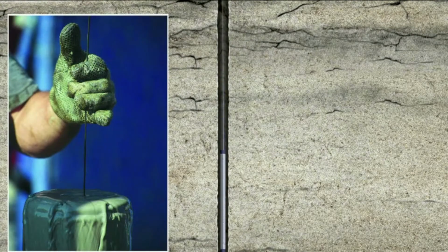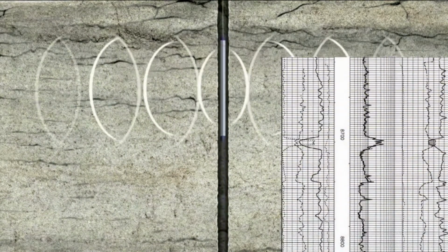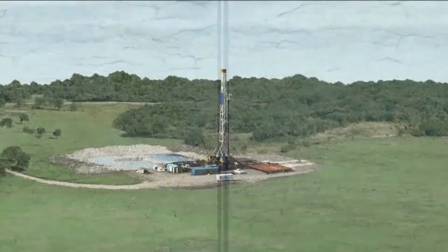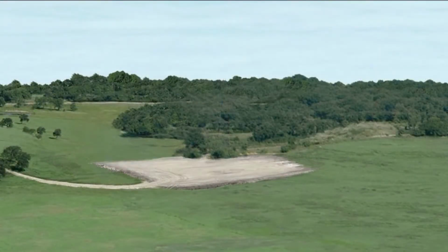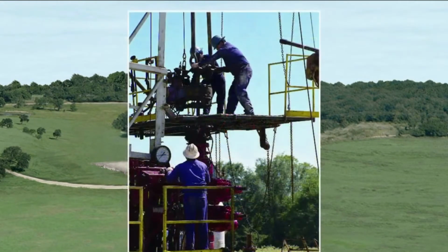Next, the logging tool is lowered to the bottom of the well on a wire line. As the tool is pulled back up the entire length of the well, data is gathered to create an electric log. Once the well has been logged and deemed to be a commercial well, then production casing is inserted in the same way as with the surface and intermediate casings, and the production casing is also cemented into the hole. Back on the surface, the drilling rig is no longer needed. A temporary wellhead is installed and the location is prepared for the service crews who will get the well ready for production.